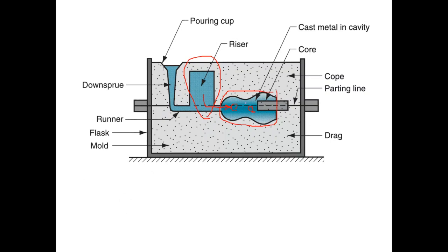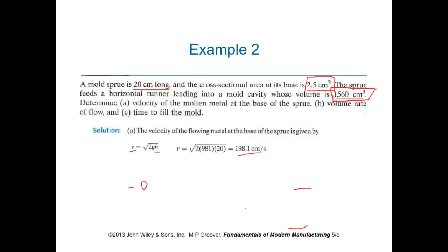The part itself solidifies first, and after that the riser solidifies. So the total solidification time for the riser is always greater than that of the cast metal. This is something that we need to take into consideration. Okay, back to the problem.